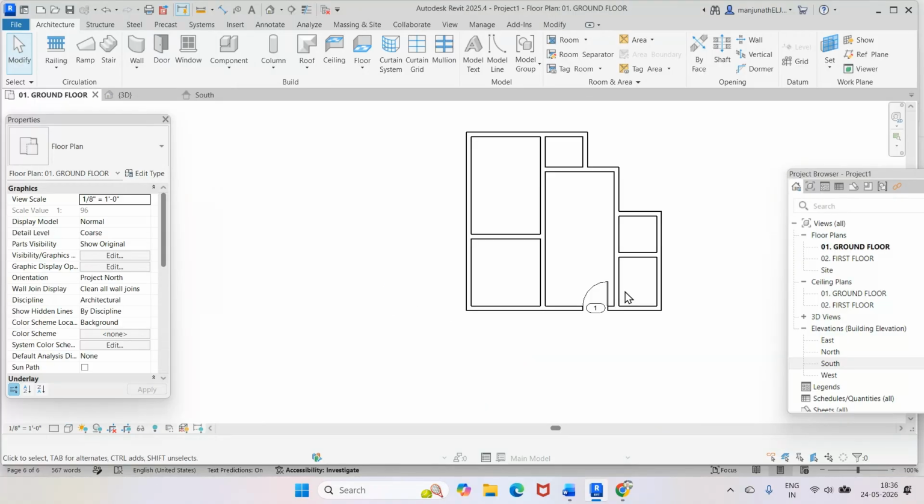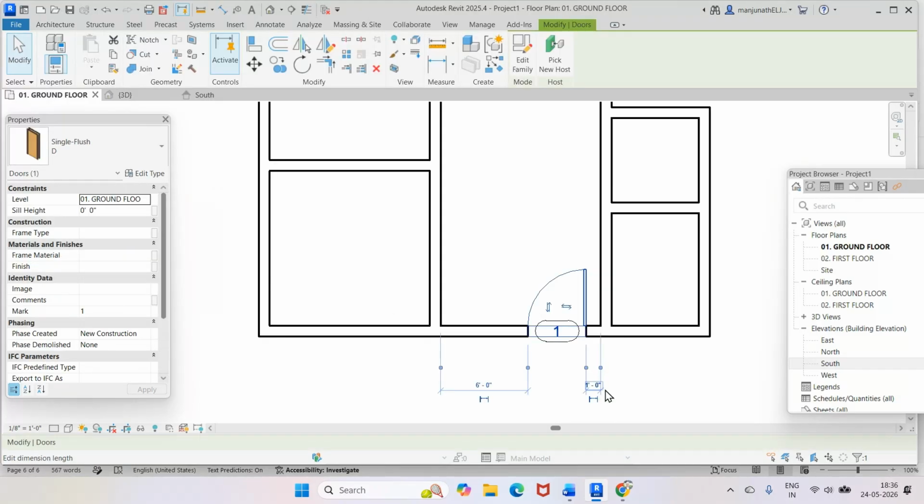Now, if I want to edit that, you just click over here. It gives the reference from the form. I can either increase or decrease it by using the space bar. Oh, sorry, like this. Okay. Now I can use the arrow keys here to increase or decrease it. So here I want to make it 6 inches.